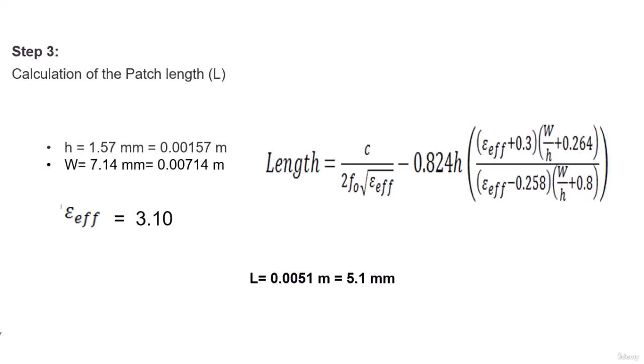So we have calculated the values of the width and length of the patch for our desired frequency. This is the analytical approach for calculating the length and width of the patch. If we know the desired frequency and the dielectric, we can calculate the length and width of the patch.